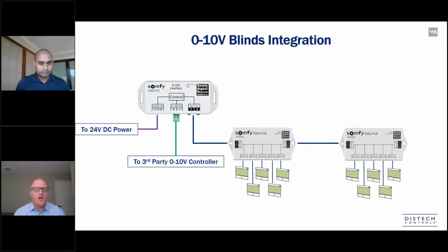I know WELL v2 has a large focus and an increased focus on natural light in spaces. And we are working to ensure that there's an adequate amount of natural light coming into the building first. And then that natural light, if we need to offset it or add more, we can use the electric light to really offset the difference. So we want to make sure that we're using natural light as our first response, instead of just walking over to the light switch and putting it at 100%, which is what we're pretty used to doing in current buildings. So that's one of the benefits.